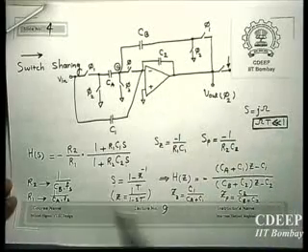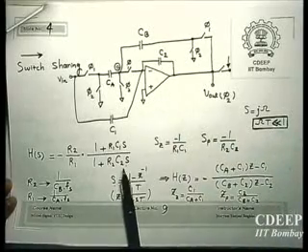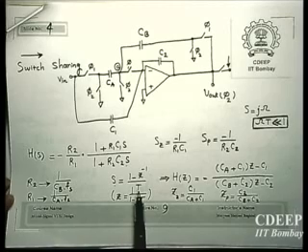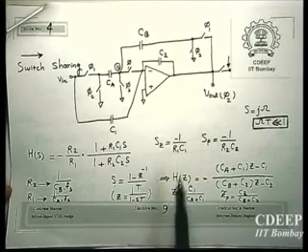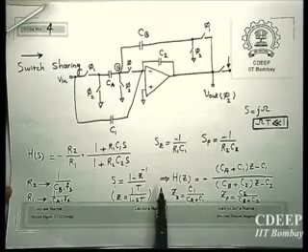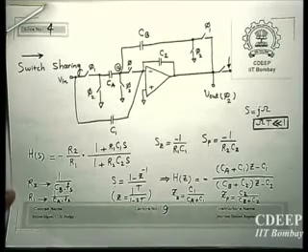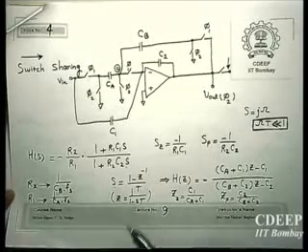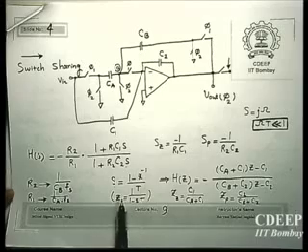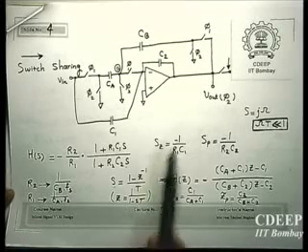And then we have the characteristic of the filter in S domain. Then we use, for example, one of the conversions. You can use any of them. Here we have used backward-Euler, so in the conversion also I use backward-Euler. By the way, you can also use other conversions, and we can see how you can in fact mix these two. Anyway, this was backward-Euler.